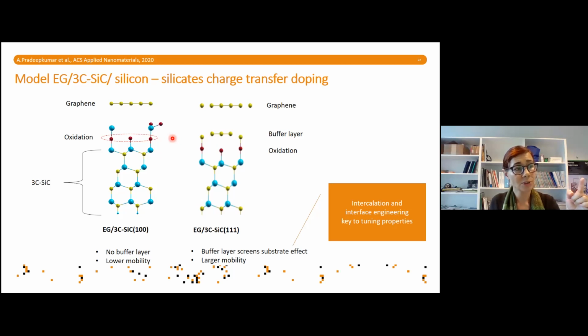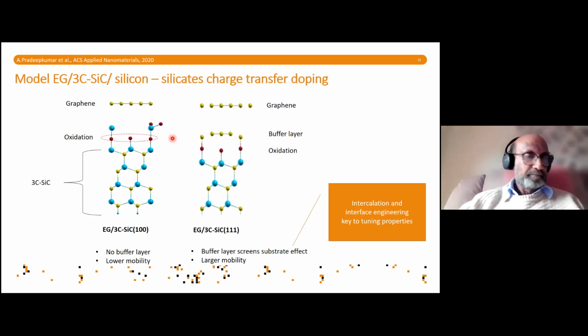I didn't show that on the dispersion curve, but the momentum matching between the free photon space and the curvature of the response for high charge concentration in graphene is better. It means that the momentum matching is going to be easier, potentially, with a high charge concentration in graphene. So also for those types of applications, this could be beneficial. It's all a matter of understanding where we are and what you can do with it.